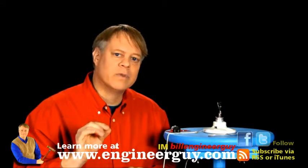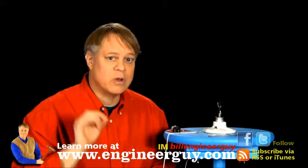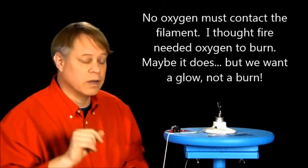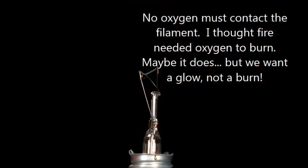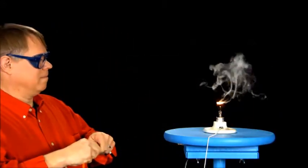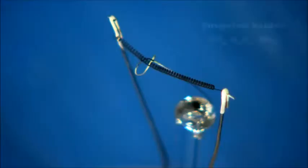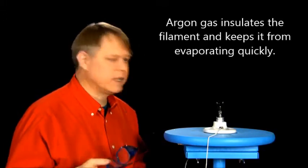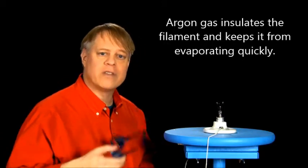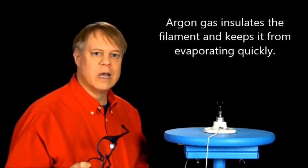One last thing. For the filament to last at high temperatures, no oxygen must contact it. Look what happens if I turn on the filament without the glass envelope. I love that. Now, if you take a close look at the tungsten, it's now black. That's tungsten oxide. To keep oxygen away from the filament, the earliest bulbs simply had a vacuum. Today we fill them with argon gas. It insulates the filament and keeps it from evaporating, thus allowing for even higher temperatures.